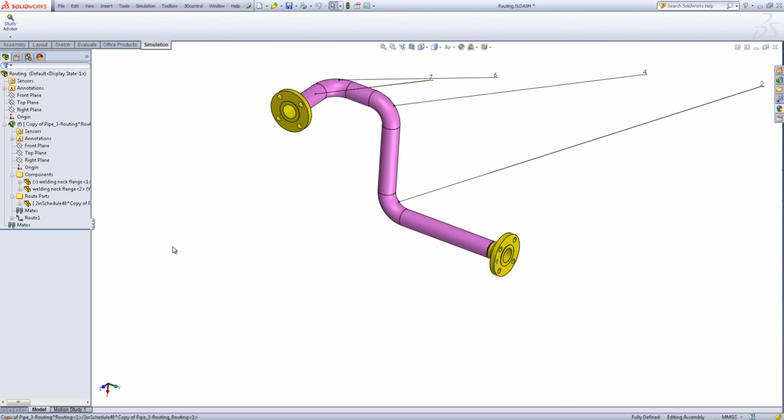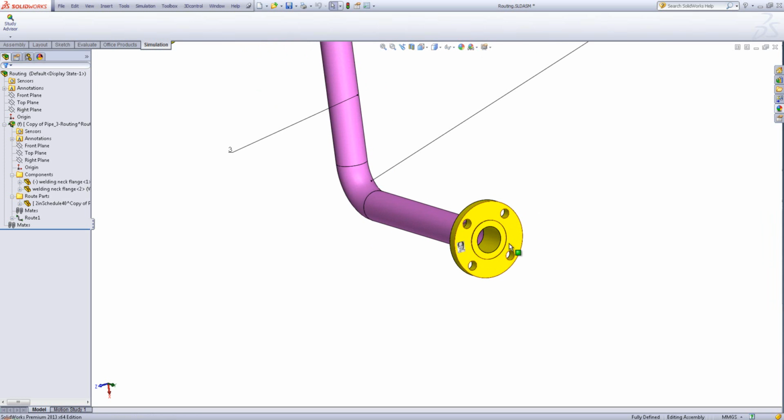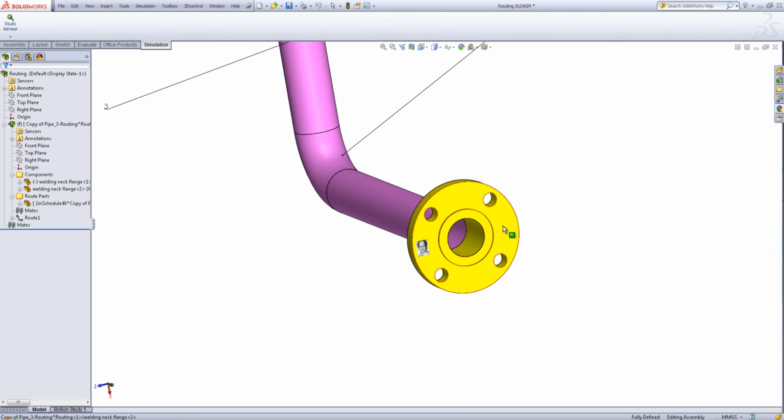So instead what I'm going to do is use a two-dimensional mesh, or a shell mesh. Hopefully, if you've been catching up on previous videos, you'll be aware of what that is now. So what I'm going to do beforehand, just a bit of pre-processing, is generate a surface body so I can negate this solid pipe now from the get-go, and then SolidWorks will be up and running, ready to go from there. So I'm going to switch to my surfaces toolbar.